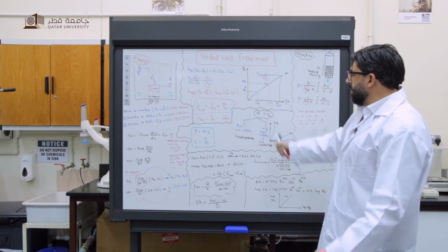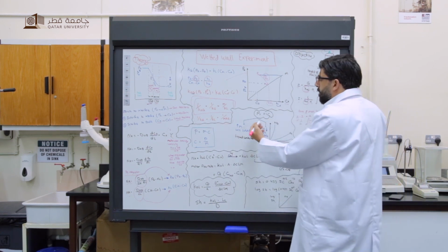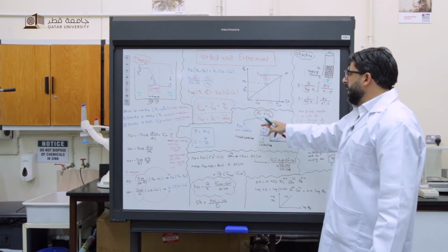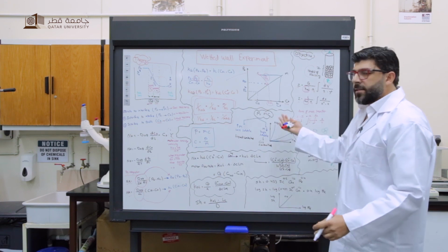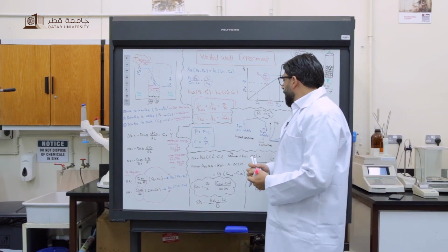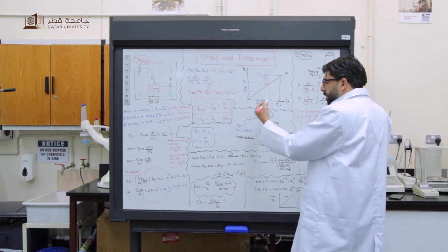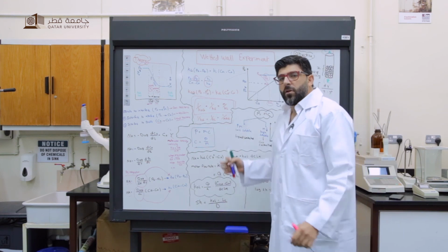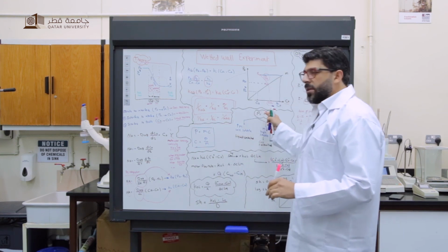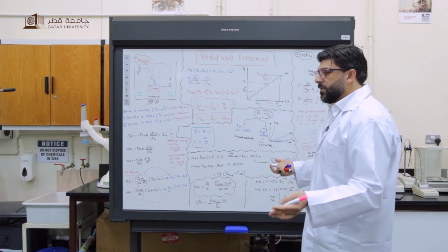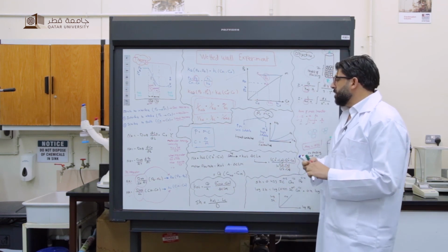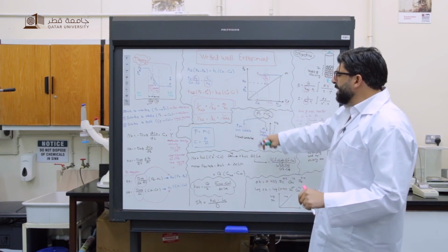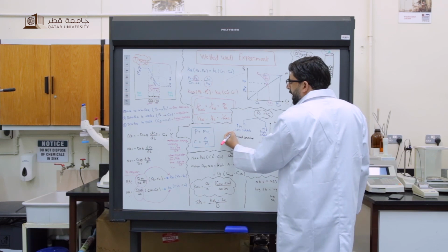Okay. Now, just to understand in more detail, we have pressure equal MC. This is the equilibrium. So the partial pressure of A equals M times C. C is the molar concentration. Now, when M increases, that means the gas is less soluble in water. This equilibrium, you can find it using Henry's law. It's known as the Henry constant in textbooks. So when M increases, that means the system is less soluble.